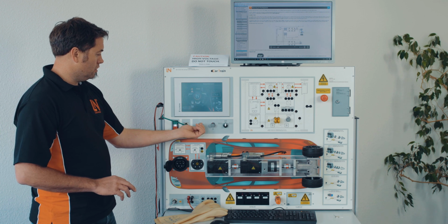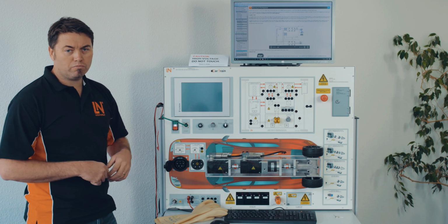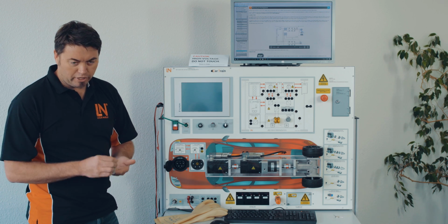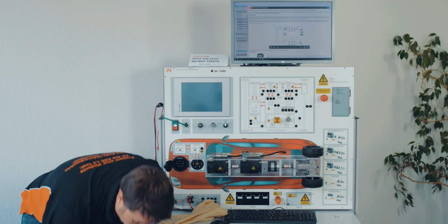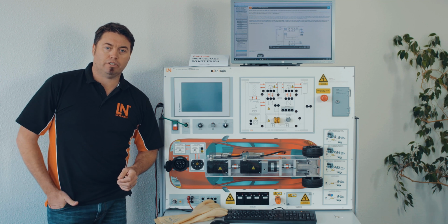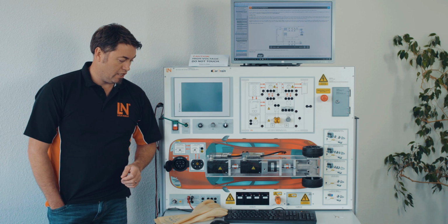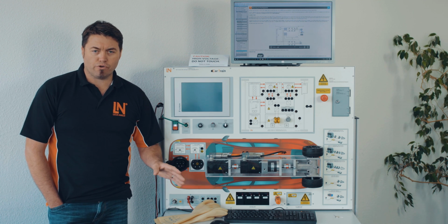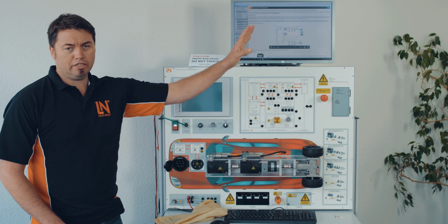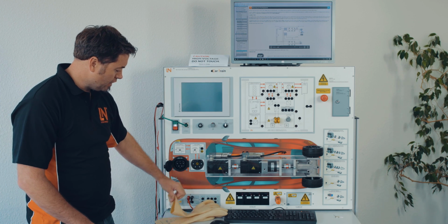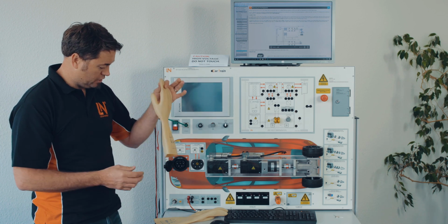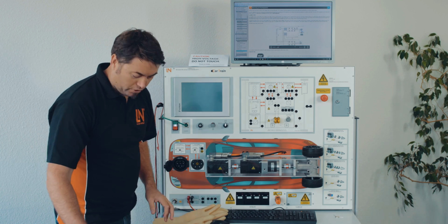We need to shut down the vehicle, of course. So this is the procedure that I was going to show you. Shutting down the vehicle: keep the key, don't throw it on the ground, keep the key in a lockout box or in your pocket. I like to say to my students, it's your life, it's your responsibility. So keep it there. Again, a smart key needs to be put away from the vehicle. Now, we need to test our gloves. So we're checking the stamp, checking if they're holding air.